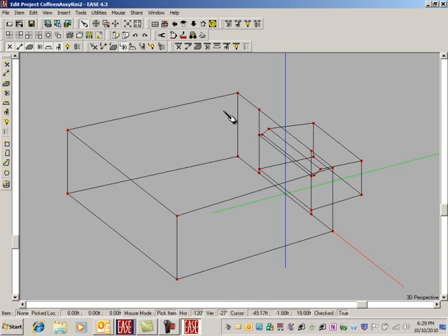We made it, but if we brought it here to 79 and just brought that wall out, this whole wall back here is at 79 feet. Well, it doesn't make much difference. We could select the face here, and we don't have a face, so we could just simply edit these to make it easy. We can edit them all, do an F4, and change this just to minus 79.